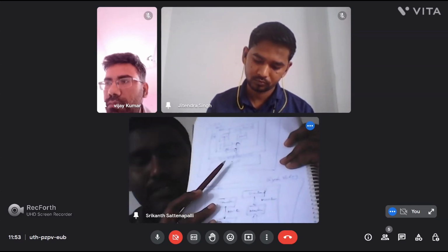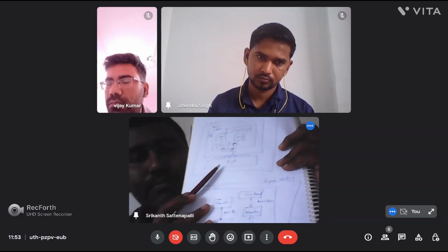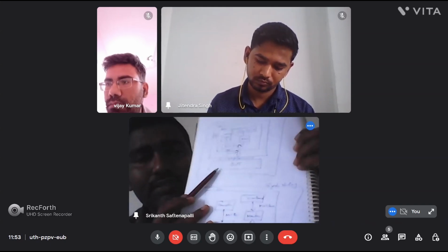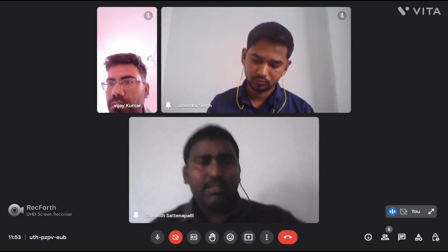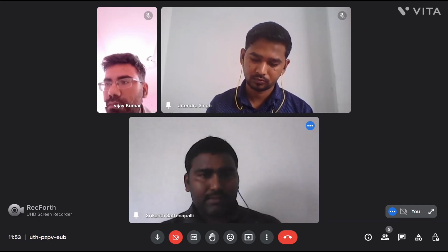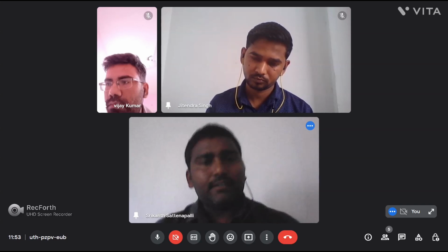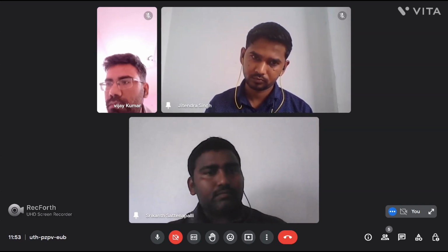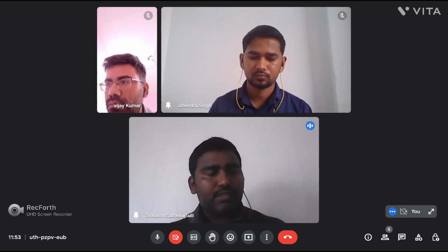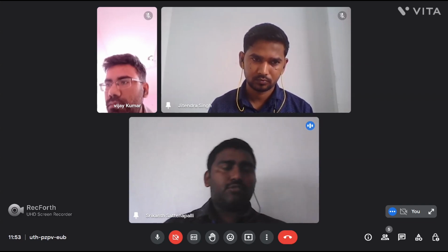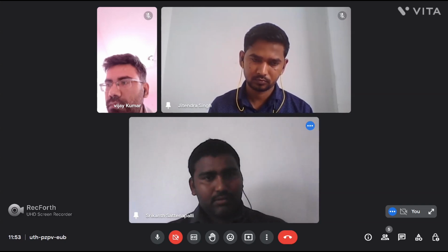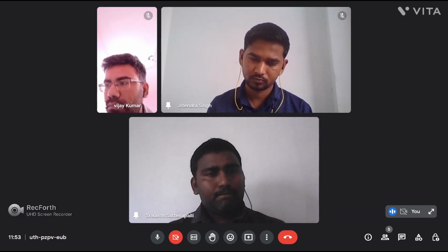In UVM, we are having TLM ports. TLM analysis port and TLM ports will be there. What is TLM port? Transaction level modeling, I think. Yes, the TLM port is a one-to-one connection, and the analysis port is one-to-many. Can we use a TLM port in place of an analysis port? No, we are not using it in place of the analysis port, because the monitor needs to connect to different parts like the scoreboard and checkers.